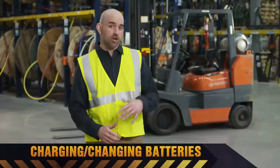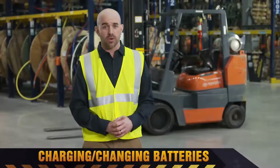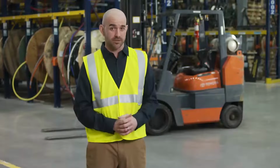Now, anytime you're charging or changing a battery, be absolutely certain you know the safest way to do it. And always wear eye and skin protection when changing a battery, since battery acid is corrosive. When you charge a battery, make sure the truck is in the designated charging area and be sure that the ventilation system is working properly. Charging a battery on a forklift is pretty straightforward.